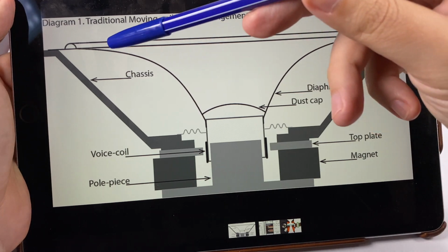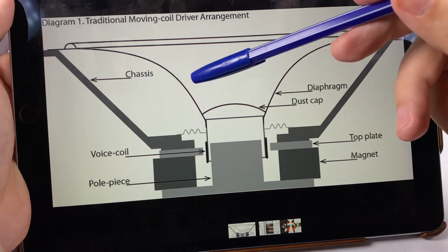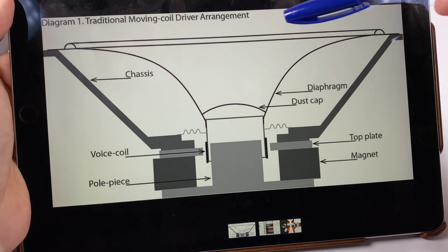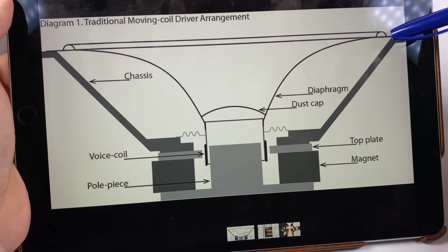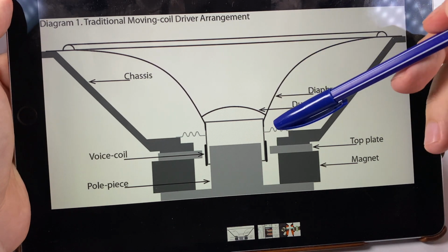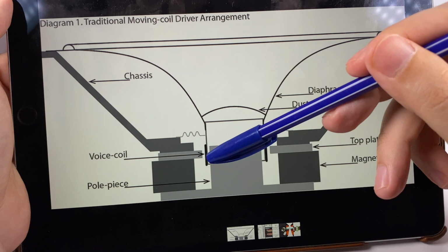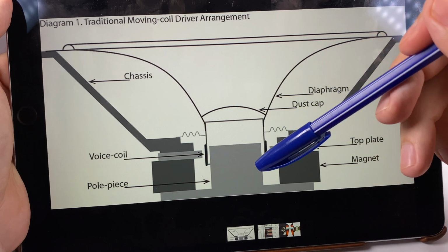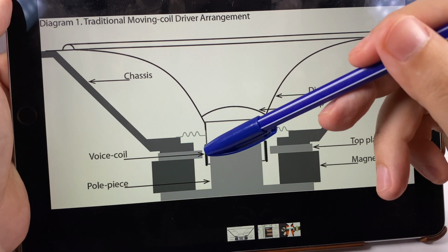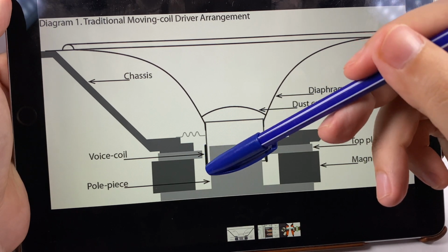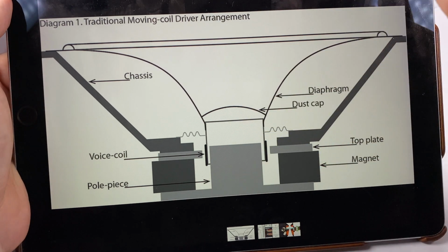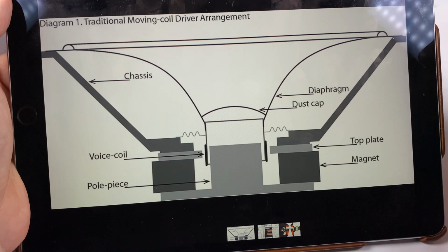And we've got some diaphragm. It can be horn-shaped or it can be just flat. It's suspended on some kind of frame, and there is a voice coil located somewhere in this static magnetic field inside. We apply the current to this voice coil and it starts moving back and forth. It moves the diaphragm and it produces the sound.